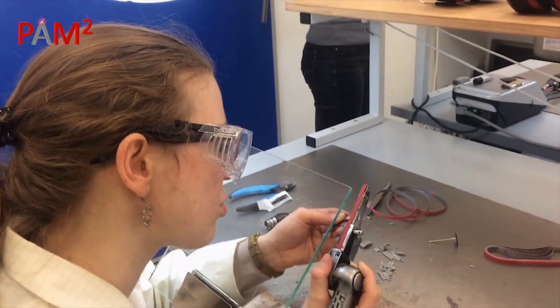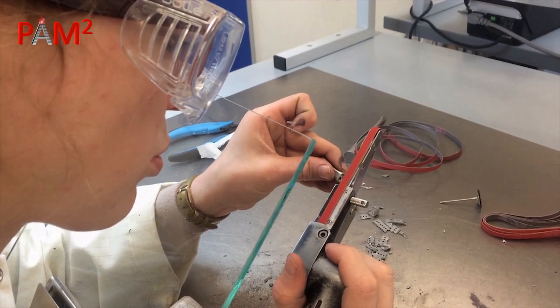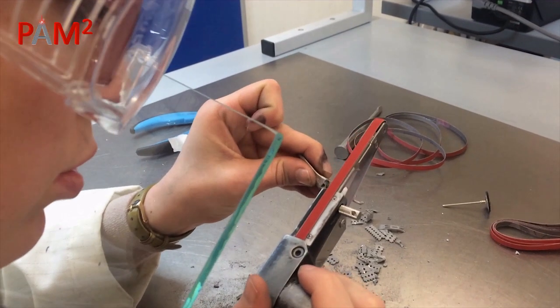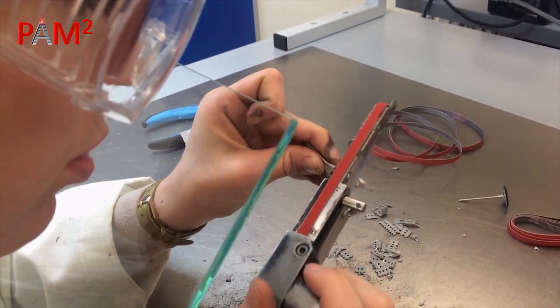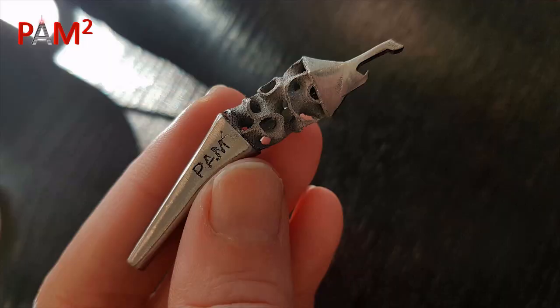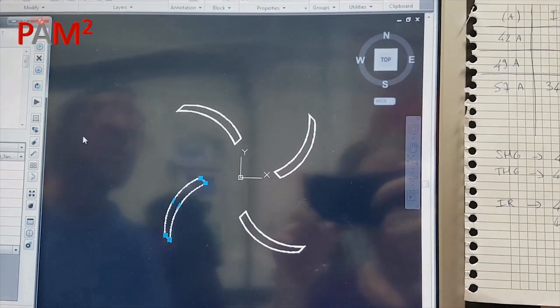Mechanical grinding is one of the conventional post-processing methods. It is an abrasive machining process to improve the surface finish of the parts. However, the use of conventional post-processing methods is challenging for small components and especially components with delicate features or thin walls. An alternative post-processing method to reduce the surface roughness is, for example, laser polishing.